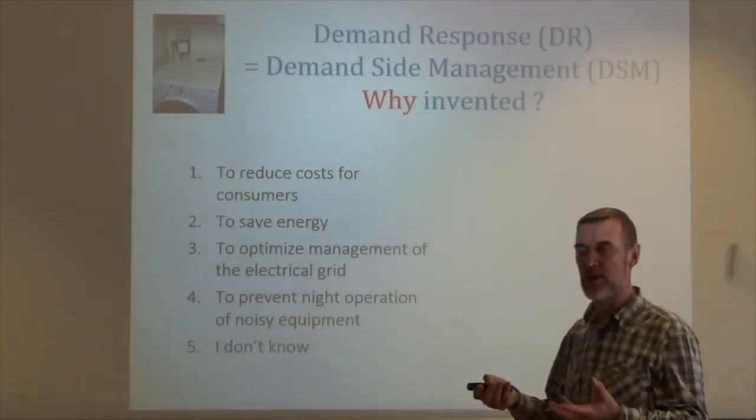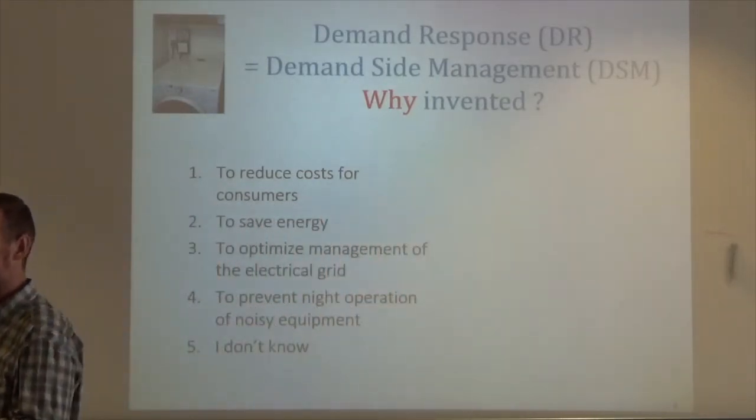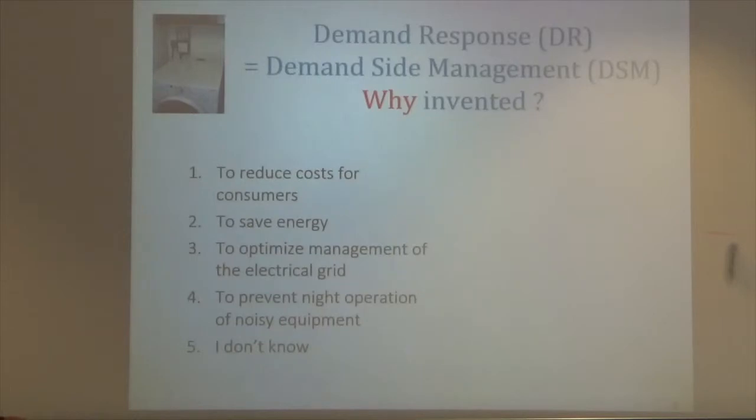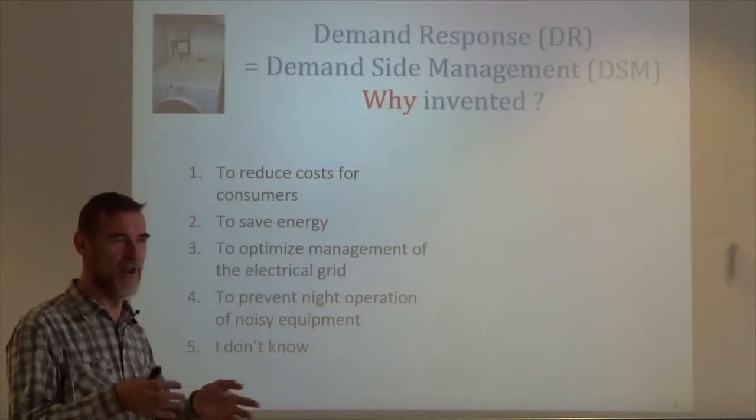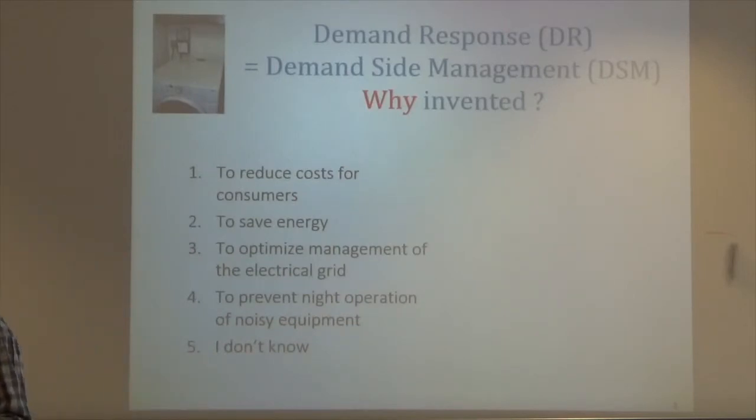If we live with a grid that has a lot of solar panels, for example, that lose 2/3 of their production when there is a cloud, like for example yesterday, the weather forecast was sunny all day, and then it was cloudy during half of the day, and the clouds came and went. So the production was very variable at a time scale of seconds compared to the forecast here. If you don't do demand response to follow that, what will you need to do?